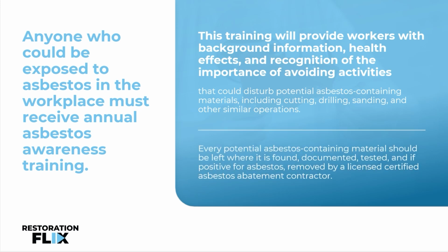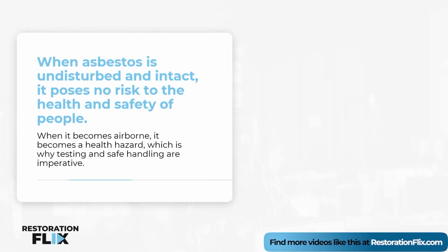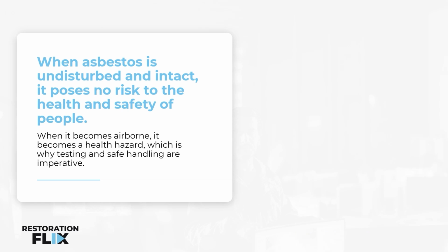Every potential asbestos-containing material should be left where it is found, documented, tested, and if positive for asbestos, removed by a licensed certified asbestos abatement contractor. When asbestos is undisturbed and intact, it poses no risk to the health and safety of people. When it becomes airborne, it becomes a health hazard, which is why testing and safe handling are imperative.